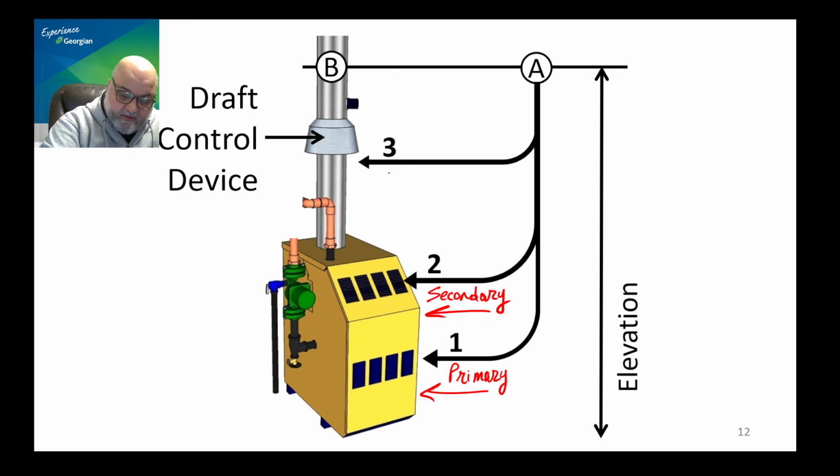And this we are going to call dilution air because it goes into the venting system and mixes in with the flue gases. So this is how air goes into the system, and it is worthwhile noting that dilution air is not something we want. Therefore, as we started the whole conversation, we add a venter motor to prevent the need for dilution